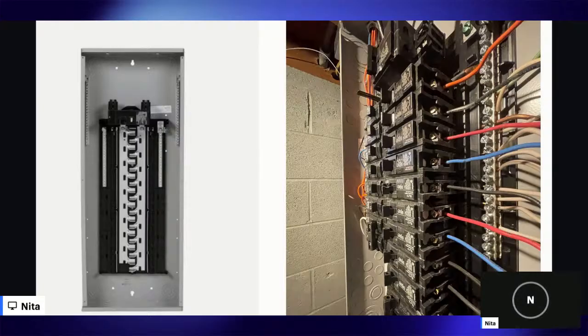Okay, just so I'm following your little circle correctly. Where that red and blue and orange and black, were those connected right above that? You're talking about that's the lug? The screw. That's right here, even on the neutral bus bar, each of these screws represents a lug. They're like clamps, right? You unscrew it a little bit and then you put it in and screw it. Yes. So that's how these wires are secured in here because they are screwed down to clamp the wire down. If you unscrew them, then you could remove that wire.